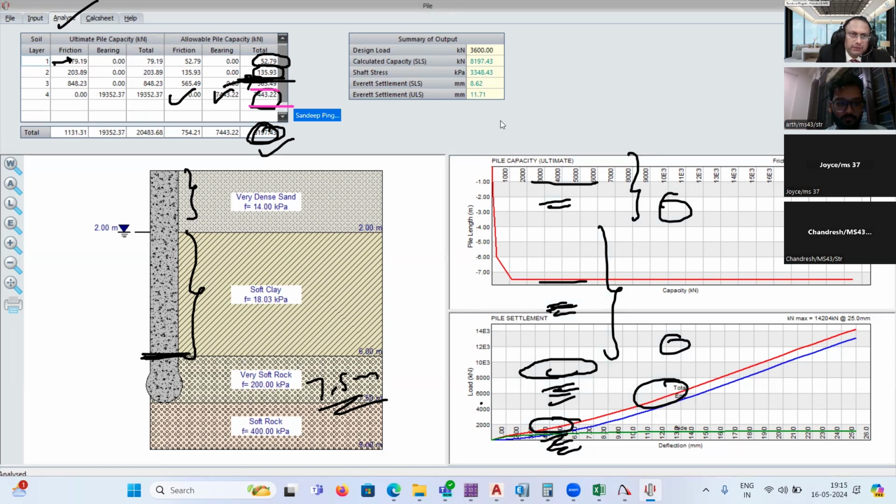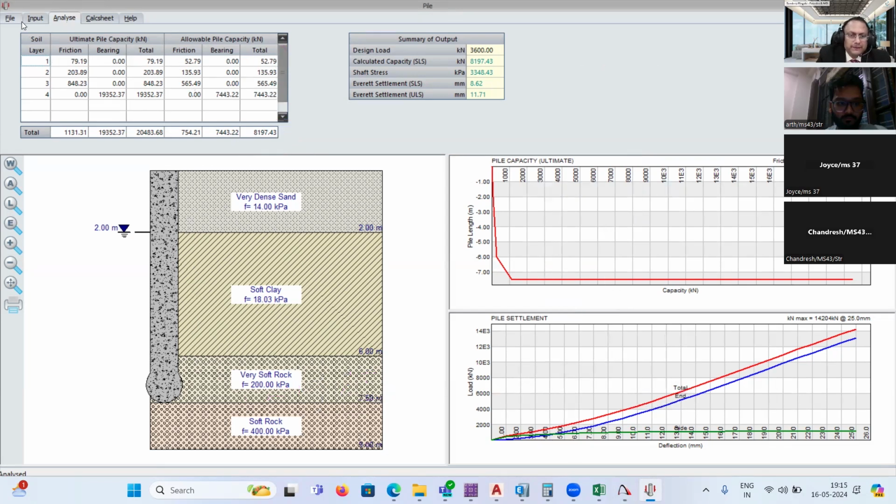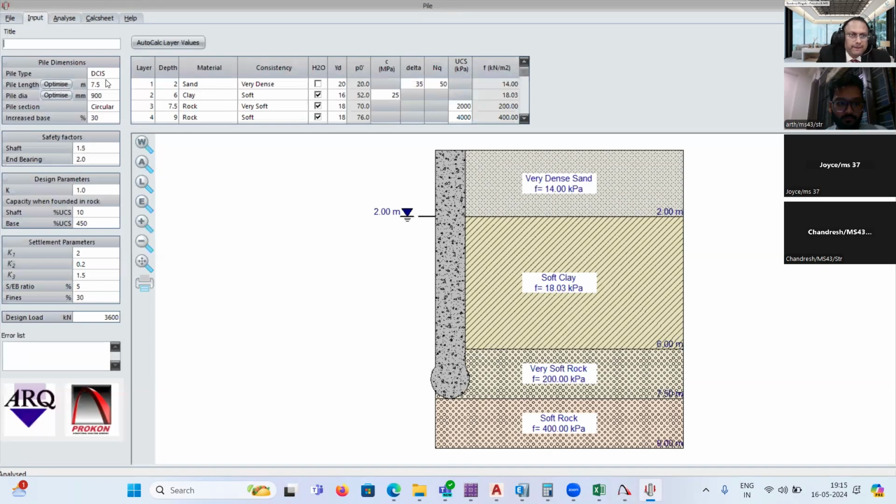So depending upon that, you need to go to the geotechnical report to see that. And currently, if you do not have anything, yes, at 7.5 meter you'll easily get 200 kPa, no doubt about it. So you can blindly use these particular values in a general way. Sir, this is for 900. So you reduce the diameter in that case. Give 600. Okay, if I give it 600.